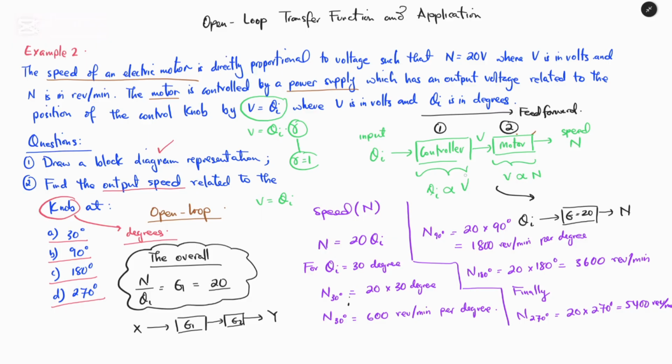In our later video, we will introduce noise. When we introduce noise, that means there will be uncertainty in the speed. In a system like this, with this block diagram, we have the controller and the motor, but no external disturbance or signal added to the system. Therefore, we have values which are consistent and linear.